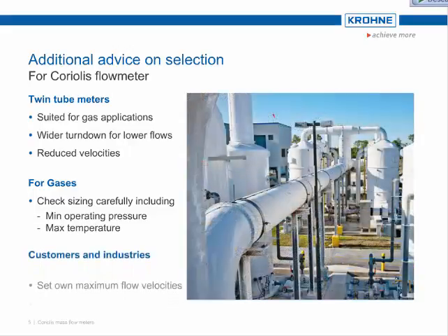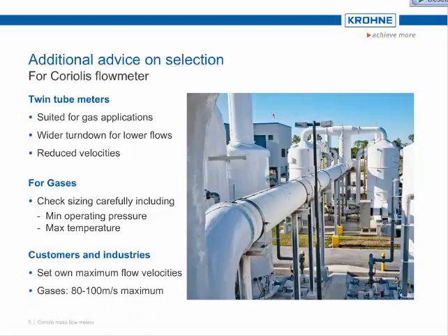Customers and industries often set their own operating maximum flow velocities. However, for gases, we advise practical maximum conditions of 80 to 100 meters per second.